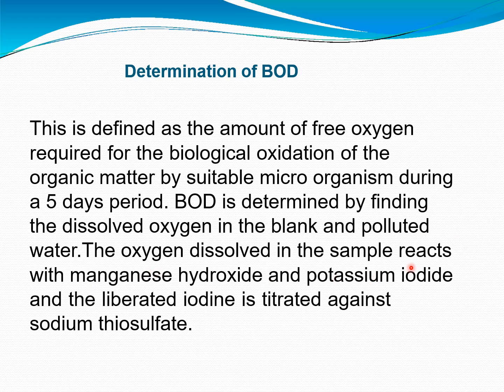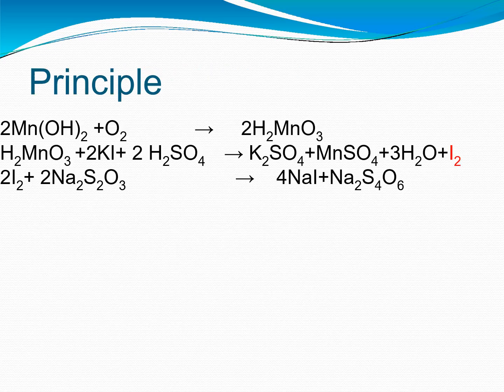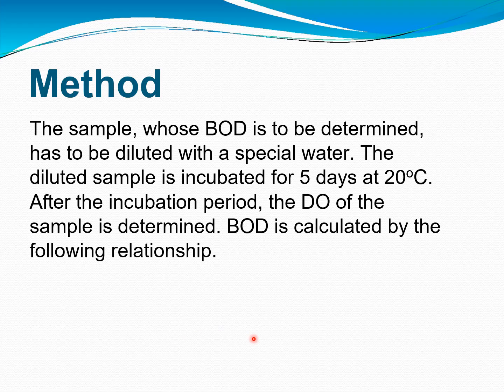The oxygen dissolved in the sample reacts with manganese hydroxide and potassium iodide, and the liberated iodine is titrated against sodium thiosulfate. So these are all the equations involved in the principle. So the method of determination will be: the sample whose BOD is to be determined has to be diluted with